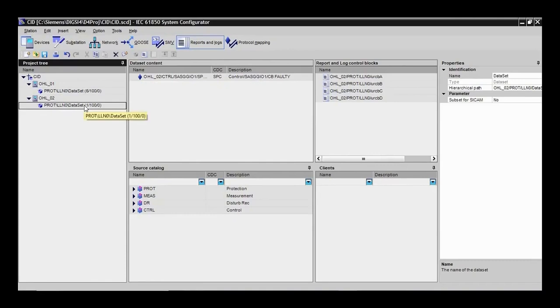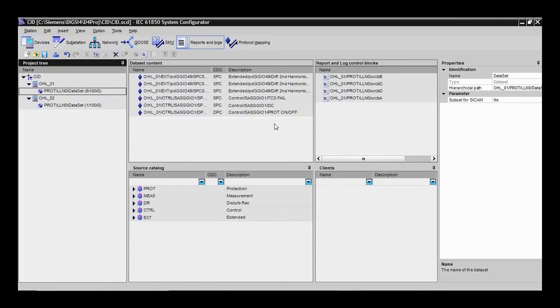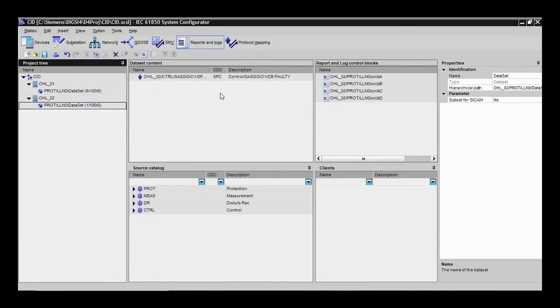All right, here is the trick I mentioned to you when I was talking about the matrix. When I told you that I would add a signal and program it with binary input number 1, but I will name it CB voltage, even though in the first relay it was called trip circuit supervision fail. But automatically, when you took it from the first relay and placed it in the second relay, what happened? It was automatically placed with the same name that was present in the long text of the second relay. So you don't need to worry or be afraid of this idea of how you will copy and paste them when they have different names. No, copy and paste them.